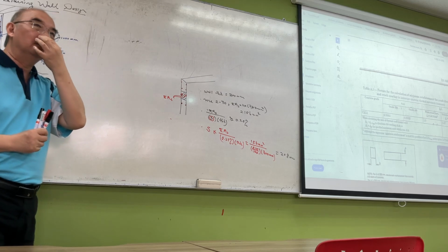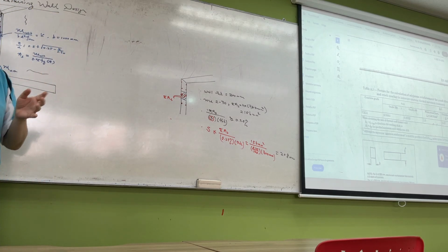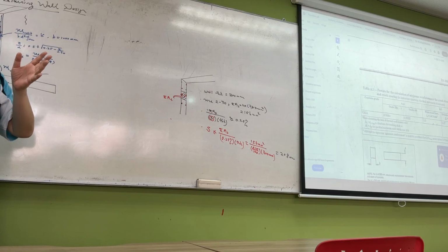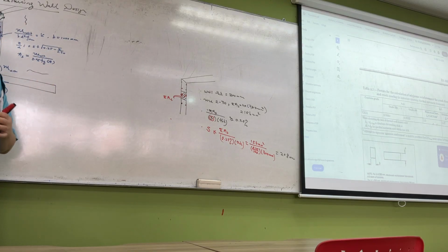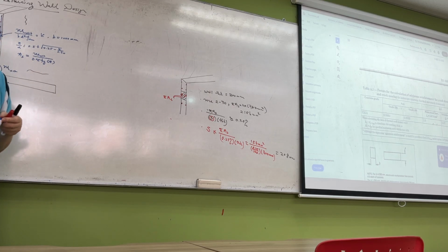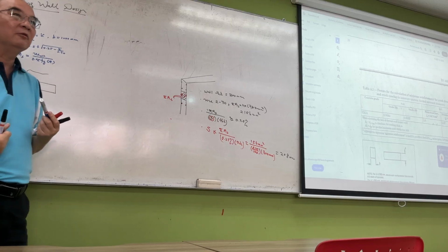So normally the idea is, I would say, people very seldom put one layer, only when the wall is very thin, let's say your wall is 100 or 75, then you put one layer. Because if you took two layers, there's not enough spacing, plus the concrete cover.